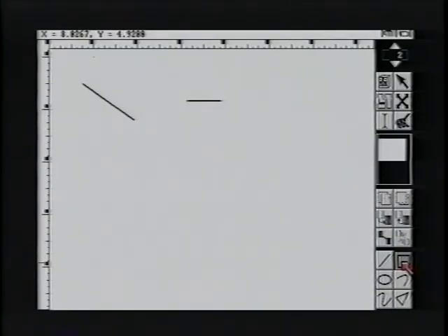The next tool is the Box Drawing tool. This works like the Line tool, except it creates either boxes or rectangles. Click on the tool, move the pointer to the spot where you want the first corner of the box. Drag the pointer away, and you'll see the box being drawn. If you hold down the Alt key while drawing, then the boxes you create will always be perfect squares. When you release the button, the box will be drawn on the page.